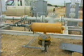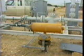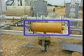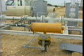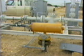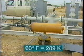The density of an NGL stream is determined by use of a gravitometer, or more typically, a densitometer. The densitometer measures weight per unit of volume as compared to water weighed in a vacuum. If a gravitometer is used, it records the specific gravity of the liquid stream, and then the reading is converted to density by multiplying by the weight mass of water per unit of volume in a vacuum at 60 degrees Fahrenheit.